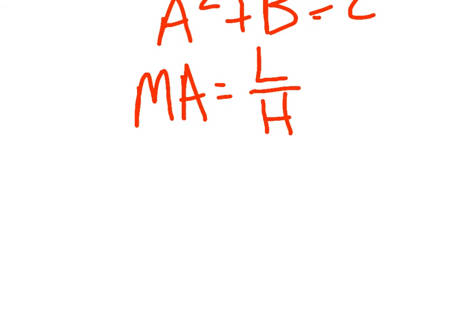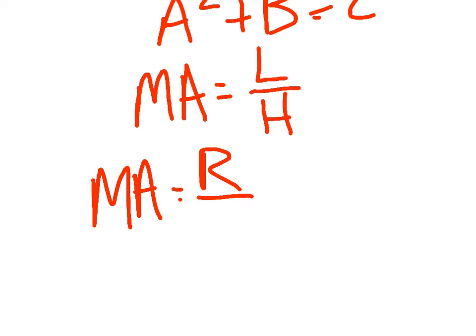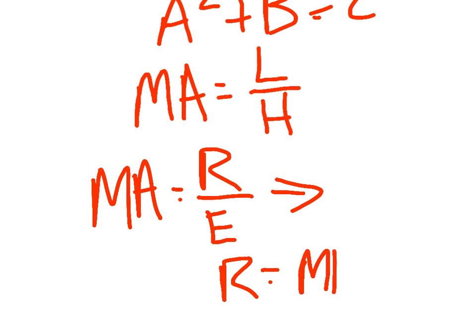And the final one, number 26, what we're looking at there, it says how much resistance can be overcome by the shearing machine. Well, we know that mechanical advantage is equal to the resistance over the effort, but we have to rewrite that. What we're trying to figure out now is the resistance, and the resistance is going to be equal to MA multiplied by the effort. So once you figure out what the mechanical advantage is, and you take a look at that problem, plug in some numbers, you should come up with an answer, and that's going to be in pounds. So give those a shot, have them ready to go for class tomorrow.